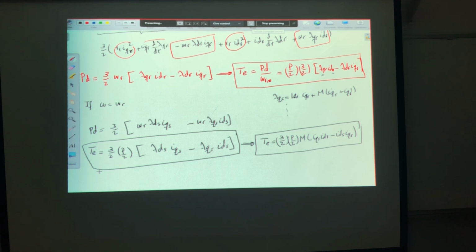what about if I can make the reference frame rotate such that all the flux of the rotor is pointing toward the d axis? Now you know that if you have a vector, the flux, it will have 2 components. Let's say lambda r has 2 components, correct?